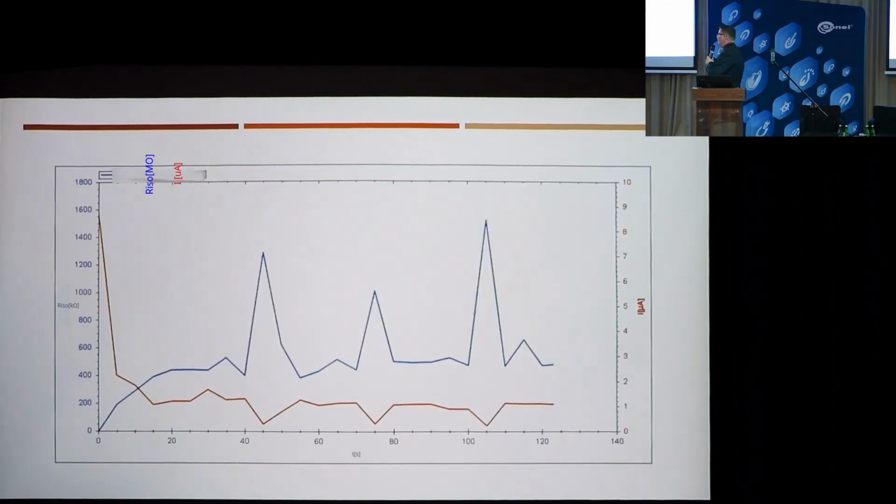So we checked the graph for this motor, and there you go. What you see in blue is resistance. The current is shown in red. The measurement time was 2 minutes. And what do we see? Well, it shouldn't look like that. Indeed, the average resistance result sits somewhere around here at just over 400. But here it's obvious something wants to go higher and something is stopping it, pulling it down.